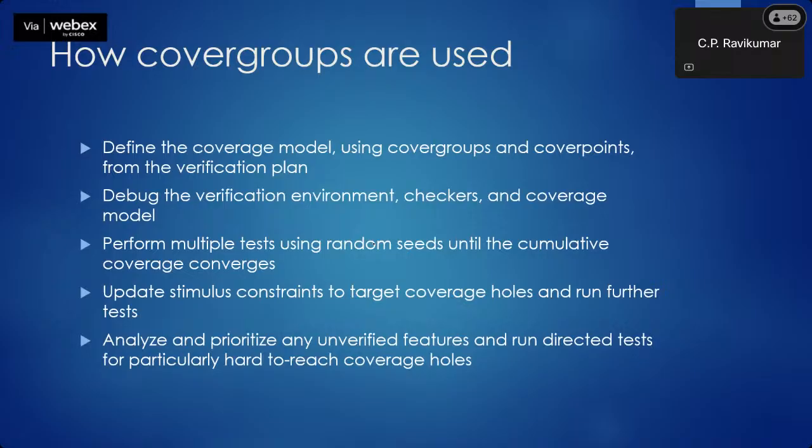When you generate random tests, we have looked at $random and $urandom_range and so on, right? When I repeat the test bench, suppose I run this more than once. If the seed is the same, then there will be no difference. It is going to generate the same sequence of random numbers. So all random number generators use what is called a seed.